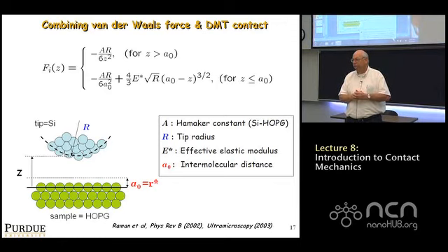There are certain clean rooms and certain vendors that seem to make cantilevers more reliably than others. They seem to have better control of the etching conditions and the preparation conditions. So the quality of cantilevers varies an awful lot depending on the fabrication facility that makes them.